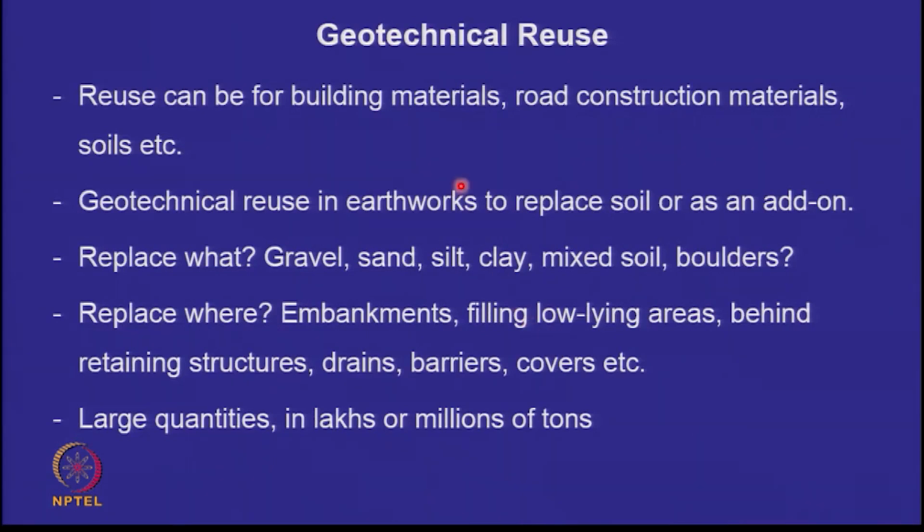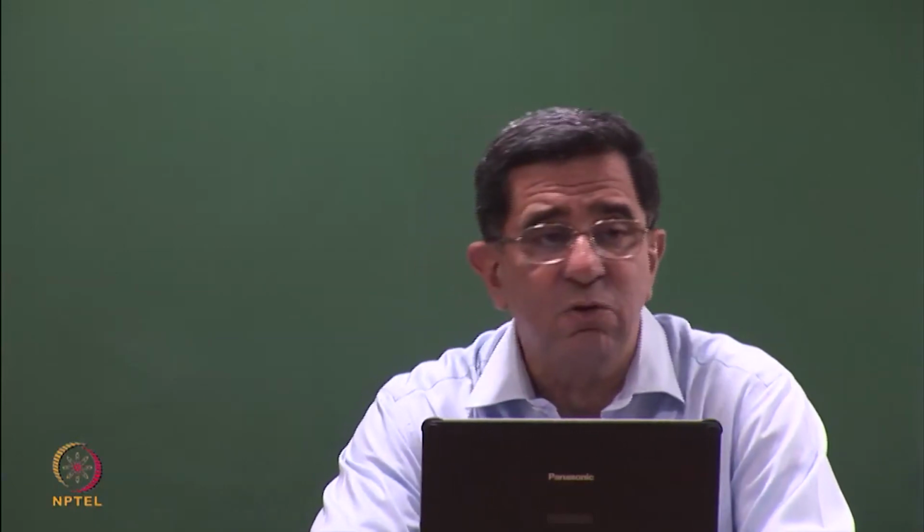So when can we, and how can we, reuse the material for geotechnical applications? As I said, in the infrastructure and construction sector, reuse can be for building materials, it can be in roads, because several kilometers of roads are being constructed, or you can use some of the material as a soil. When you construct a road, there is of course the pavement section at the top, but do remember that beneath the road there may be a long embankment, a few meters high, running for several kilometers. So there is a huge potential if waste can be used as soil.